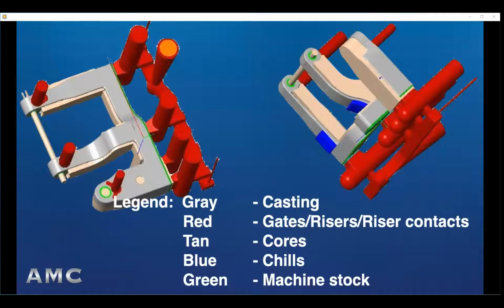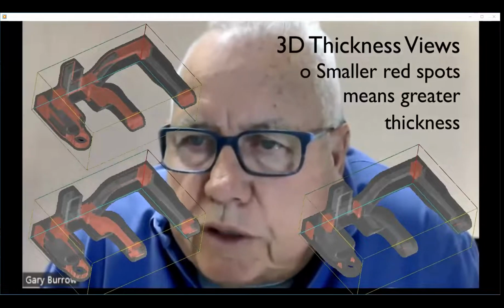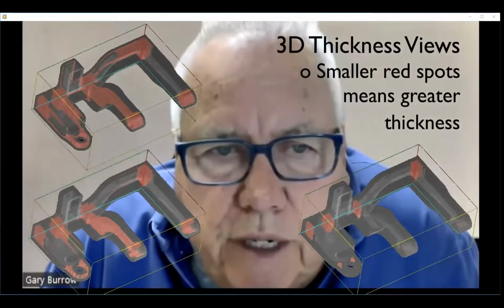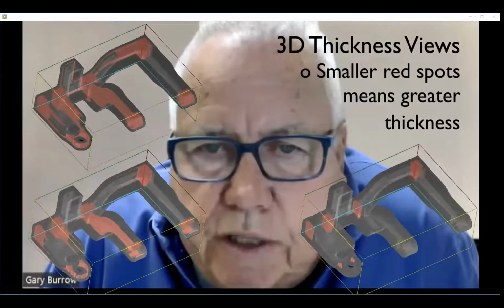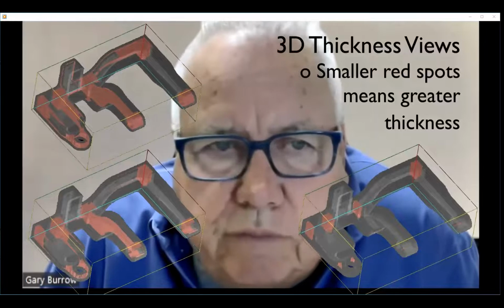The reason that process interface geometry is so important in casting production is that mechanical properties achieved in a casting are accomplished with process interface geometry. Here are images of some of the internal thicknesses on a 3D basis that guided the design of the riser locations of gating system to fill the mold cavity.